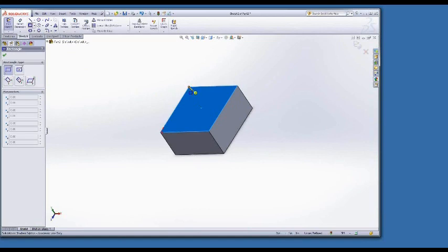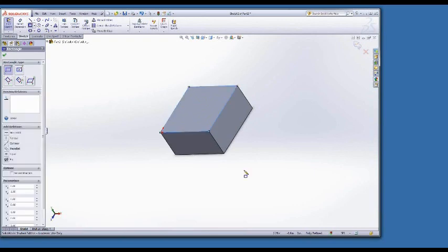you go to your current shape, whenever you get to certain features, you'll see these little circles and boxes light up. The circle represents my endpoints, and the boxes represent the midpoint of a side. Okay, so I want to make a rectangle that is exactly the same as the top of that. But I want to add to this total shape something a little bit different.